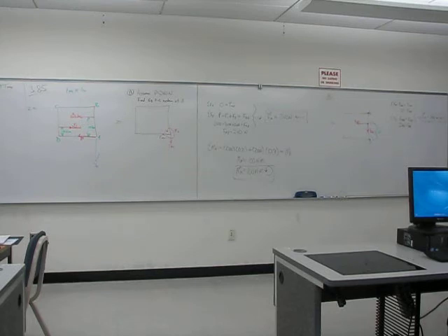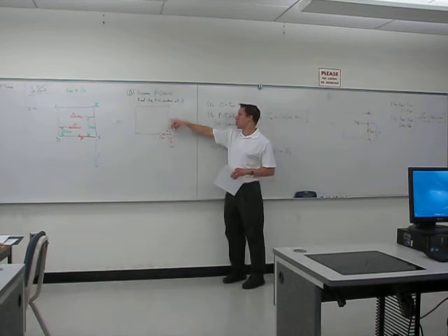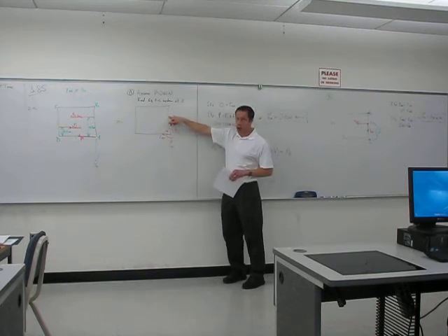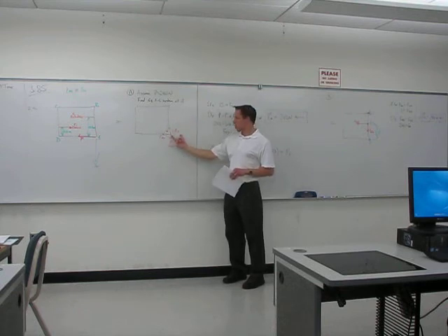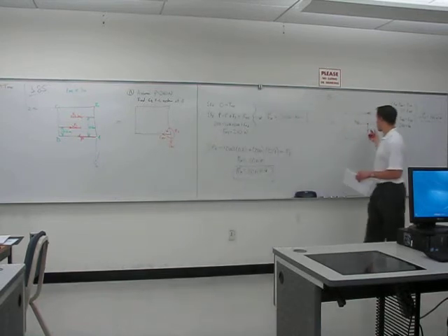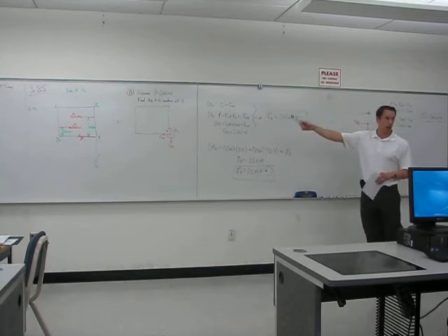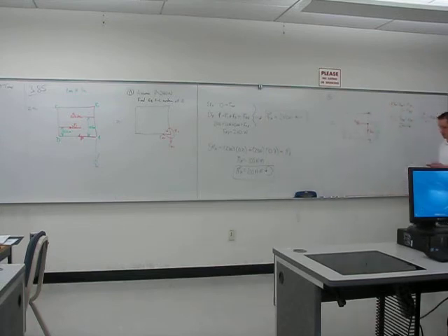And that should make sense, because what we're doing here, if you remember what I described before, is we're just taking the force that was applied at the point A, and we're just moving it to another point. So it's going to be the same force. Now the point that we're moving it to is going to be one where the moment that we add into the picture is going to cancel out the moment that we have in this picture, so that the end result is there's no more moment. Just the fact that we're applying the force at a different point will create the rotation that we would get from either of those two pictures that we see before.